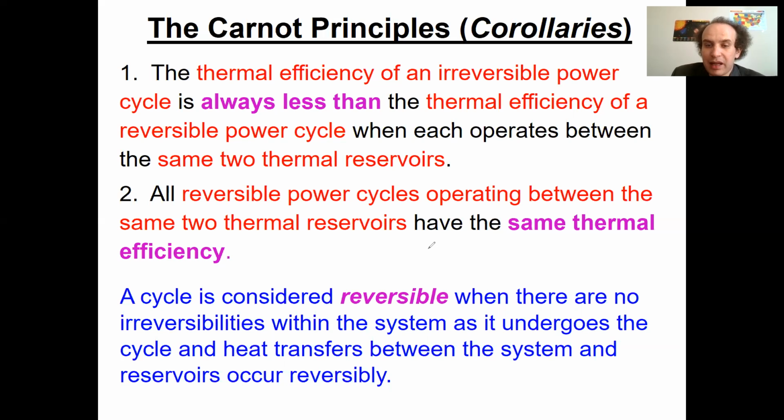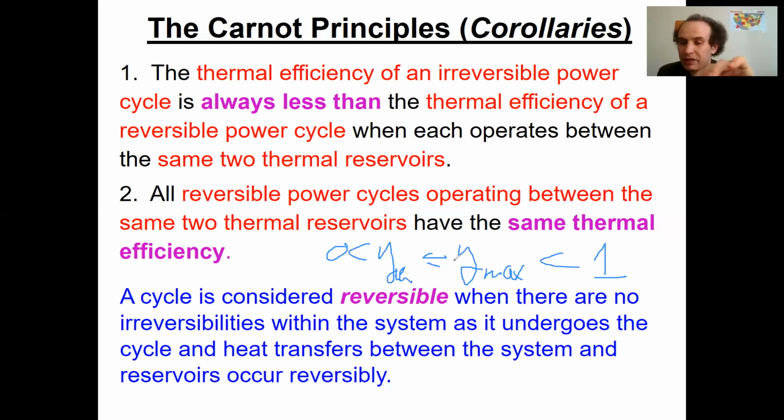Otherwise, I can say, you remember we talked about thermal efficiency. Thermal efficiency should go from 0 to 100%, right? To 1. Correct? But now I can say that it should be no larger than some maximal efficiency, which is less than 1, right? And that gives you the second law. You cannot have 100% efficiency. You have a second reservoir. You should lose some heat. You should pay some penalty. That's how you pay. And this maximal value will depend on temperatures only. Actually, on two temperatures, TH and TL.